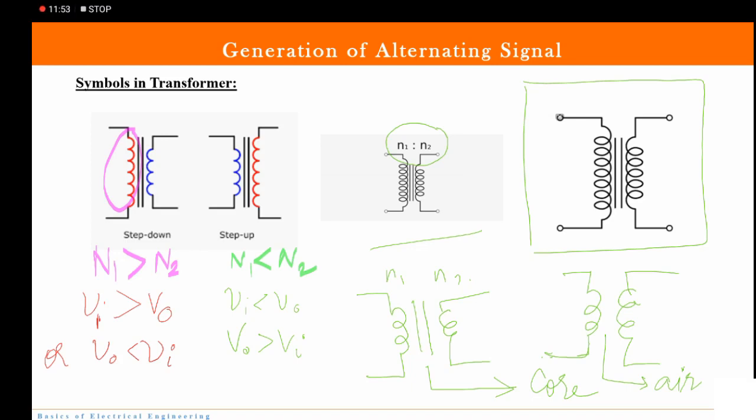Fine. Now why do we do that? Because by increasing this level of the voltage, the efficiency of the whole system also increases. And actually why does this increase? Because by increasing the voltage, the losses are reduced. So in turn, the efficiency increases. Okay, step-up transformers are used near the generating stations.